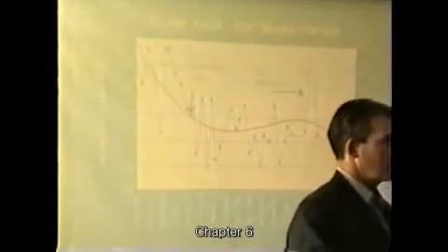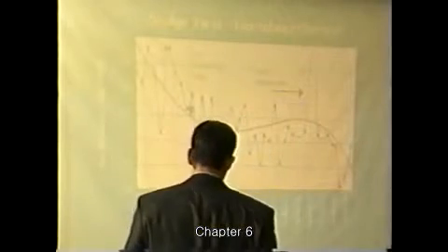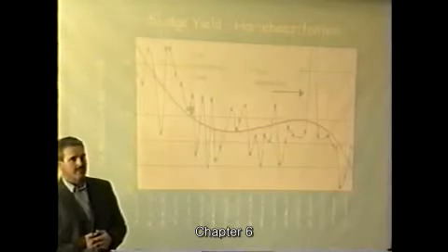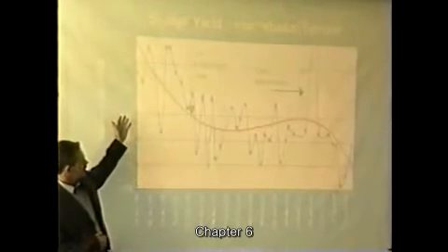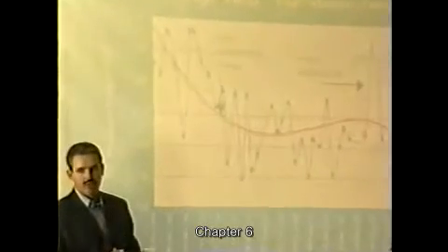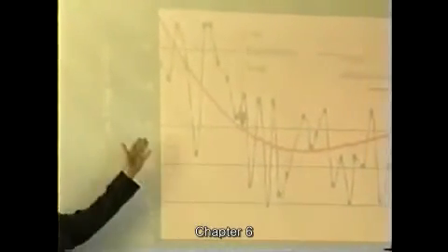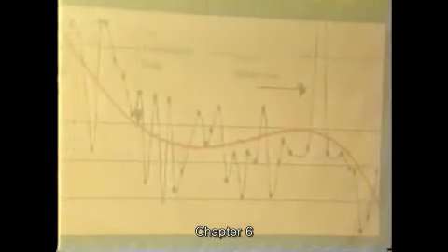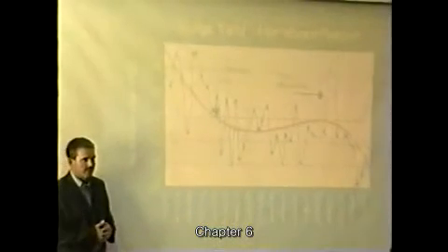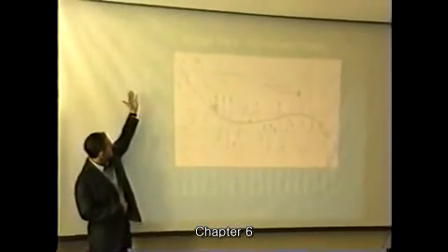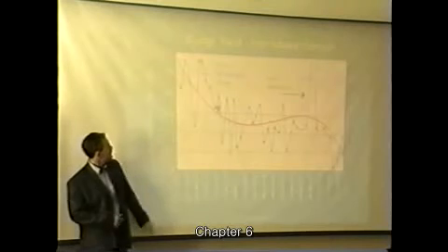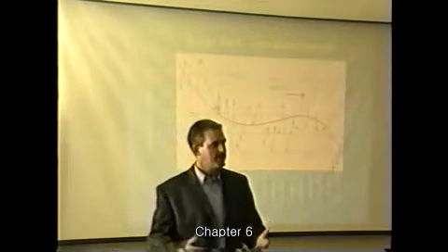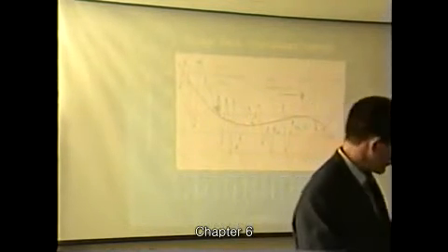Once again, we had to convince them to reduce their sludge wasting rate to allow us to contain a lot of mixed liquor in the system. And so once again, we confirmed what we saw at the petrochemical plant, reducing sludge production by at least 50%, dropping it from approximately 0.3 to less than 0.2. That means you have 50% less sludge to dispose of.